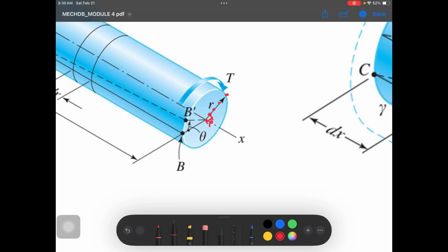That's what we call rho. And then, if you want to get yung stress dito naman sa second point na to, you need to get yung distance from the center up to this point kung saan mo gustong i-evaluate. This is now your rho na gagamitin.